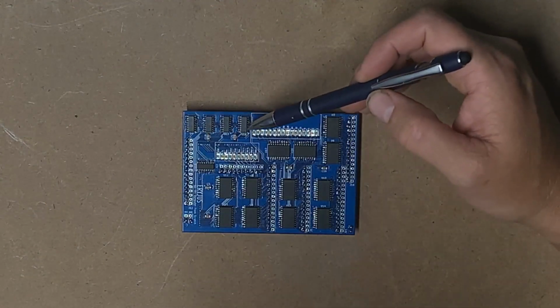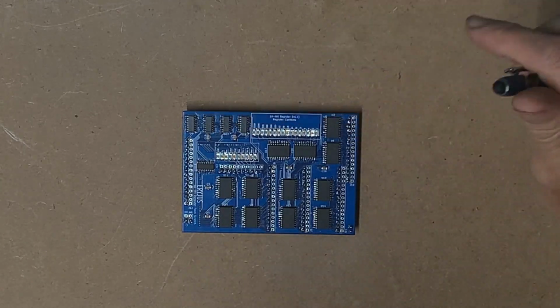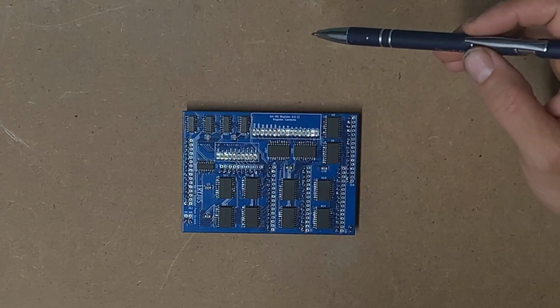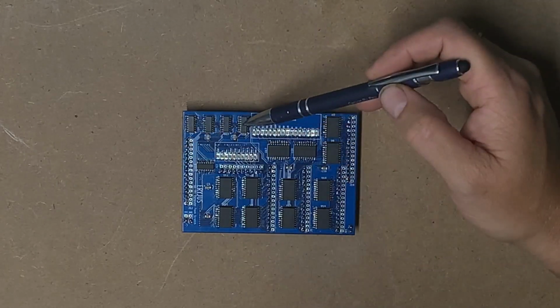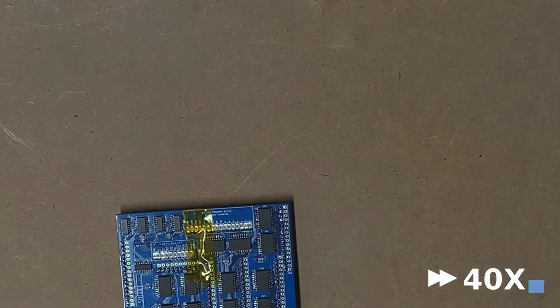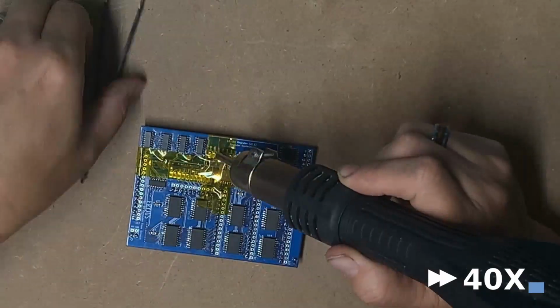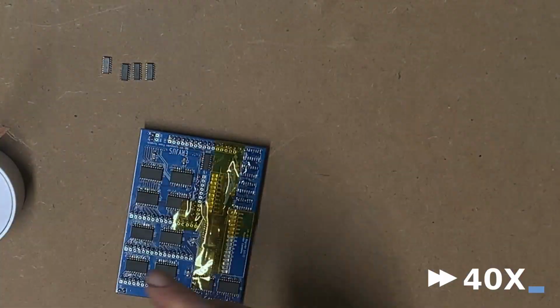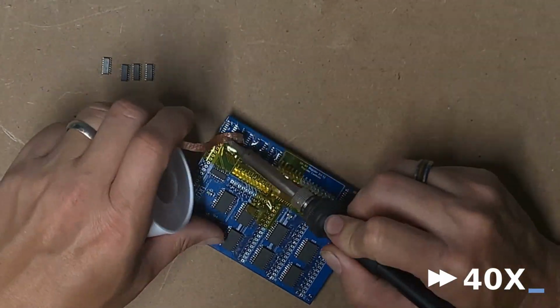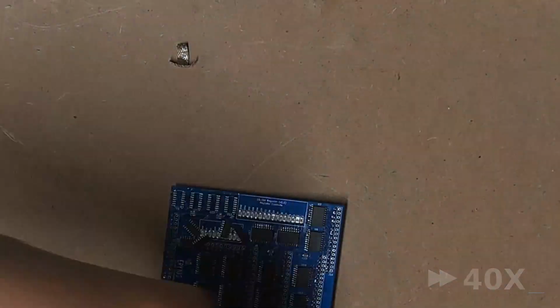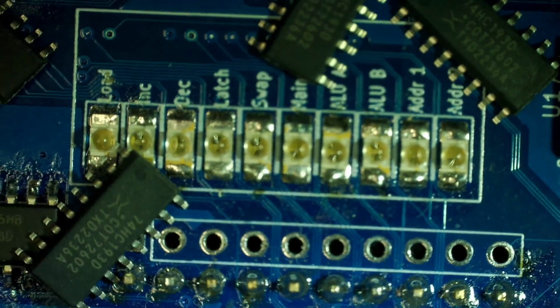Okay, I've decided to start by replacing the counter ICs on the program counter. The reason I made this decision is that I could go down the path of fiddling with the timing, but the problem is that once I replace these, I have to go back and fiddle with the timing anyway, to make sure that's tuned. So rather than wasting time doing that first and then doing it again, I'm going to save the timing fiddling with the control logic to the very end. Okay, let's see here.